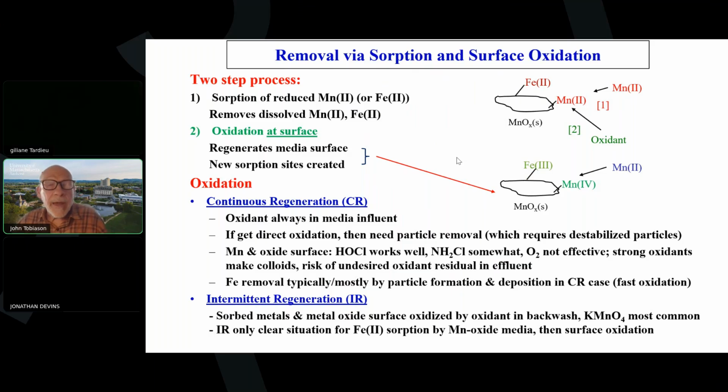It does in the time frame of a distribution system, days or weeks, multiple days, but not in 30 minutes or an hour. It just doesn't happen. And that's a myth that's perpetuated in textbooks all over the place, that free chlorine oxidizes reduced manganese to particles just like ozone, chlorine dioxide, or permanganate. And it's just false. It's not true.